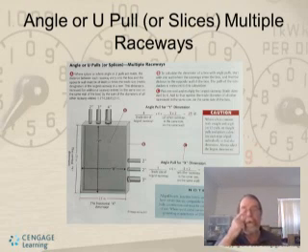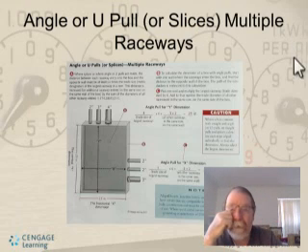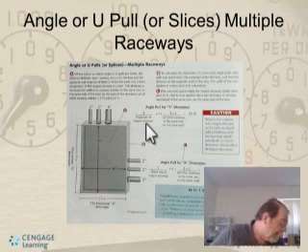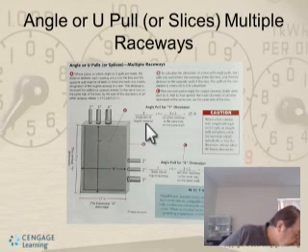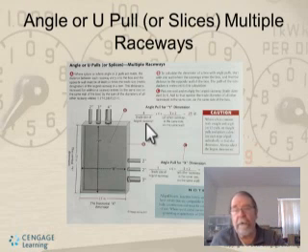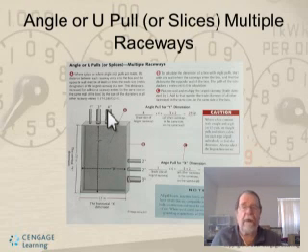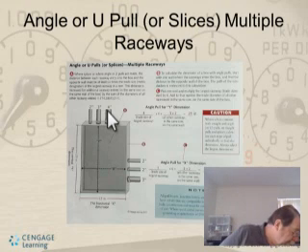Now, if you look on this drawing here, you have the number of raceways. Okay, trade size of the largest raceway is 4 inches. And multiply that by 6, and then you have the 3 and the 2-inch raceway, and that's 29 inches. That's for your Y dimensions. Okay, that's just the depth or the height of the box, not the depth. Okay, now the X dimensions is the same thing. The largest one here is only 3 inches coming in.